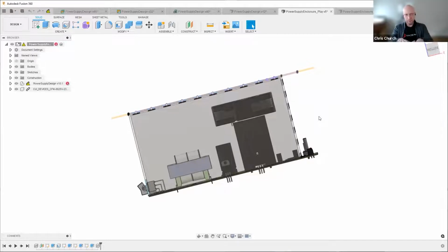So it's pretty long, because one of the things you definitely want to avoid, and this is one of the things that our team will be looking out for, as we talk about manufacturability, is if that fan is attached to that enclosure, and then we have to put the PCB on there, we don't want to be in a fiddly situation where someone is trying to reach through and trying to plug in a little connector because they've only got 5 millimeters of space between the two to assemble it. So it's good that that cable is long enough, but it can create some other issues that our team would call out.